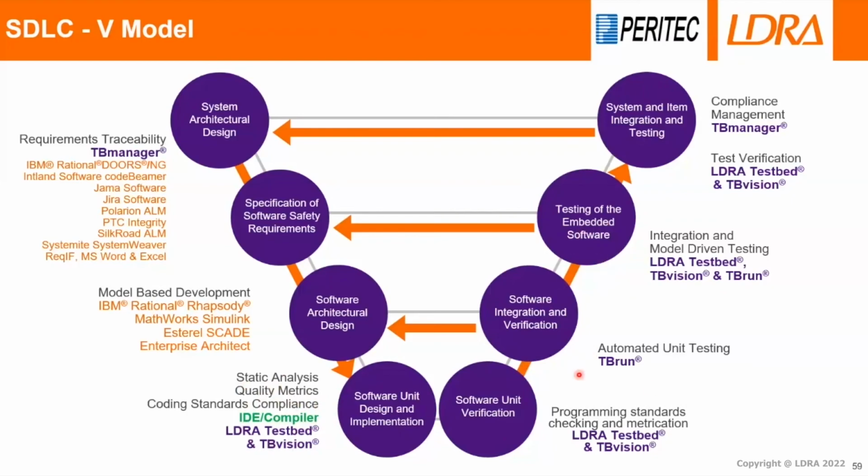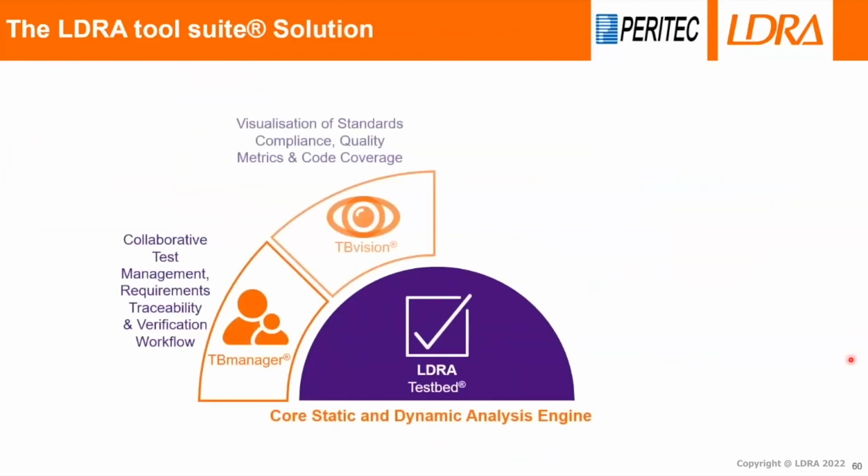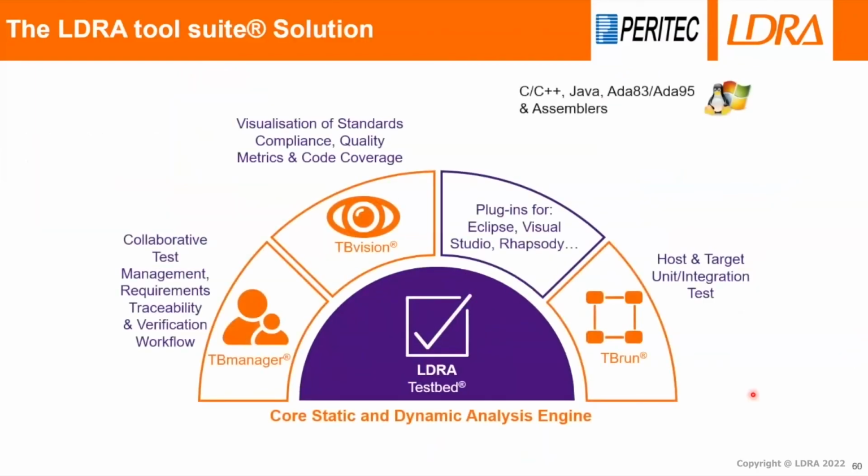So the LDRA TB Vision and TB Run modules will help you with automatic test case generation and execution for different levels of verification for the code generated. Looking at the solution from the LDRA tool suite, we have the basic module TBrun's foundation, TestBed, which can do the static and dynamic analysis. On top of that, we have the completely automated TB Run module for unit or integration testing. It can do the unit or integration testing on any target environment or on the host environment.